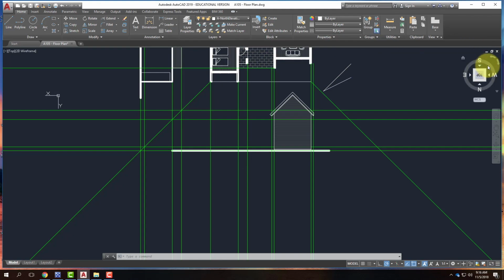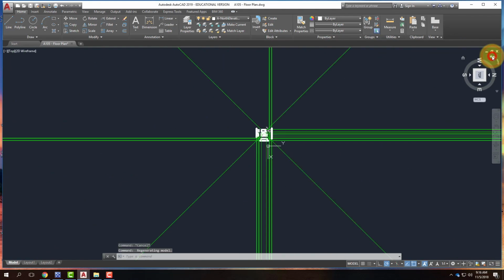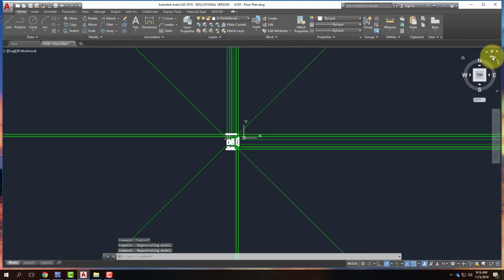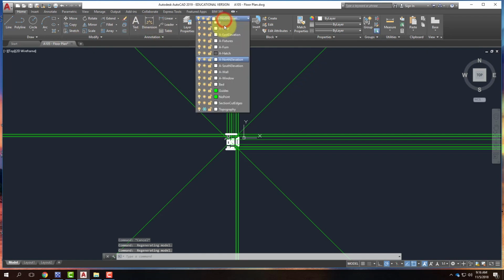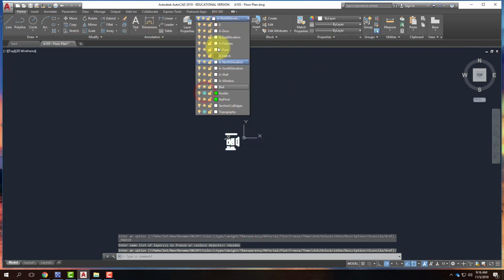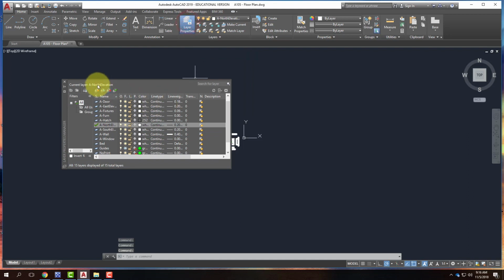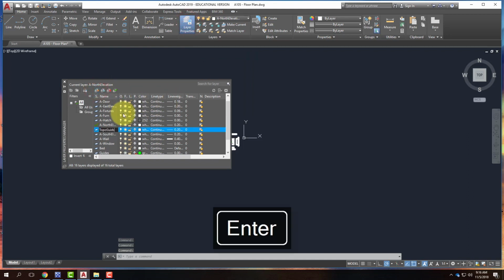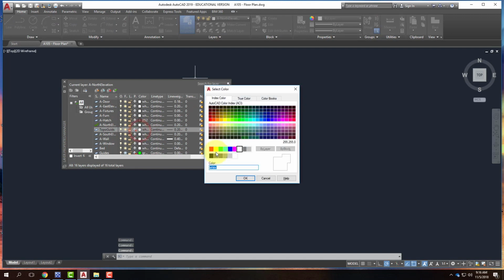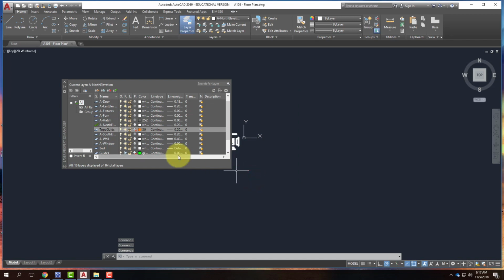So I'm going to switch back into my south elevation. And I'm going to turn off my current guides and I'm going to create another layer for another set of guides. And I think I'll call this one Topo Guides. I can't even type. Once again, it's going to be a non-printing layer. The color, I'm again going to choose green. I wonder if orange would show up for you. We'll try orange and see if it shows up on there.